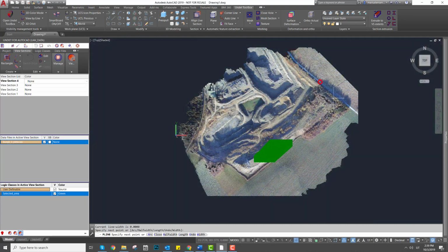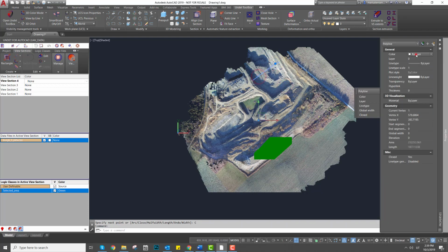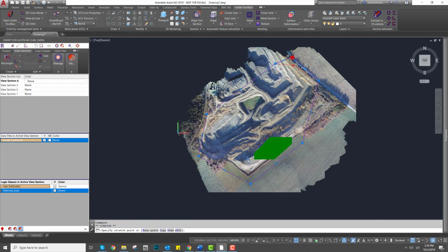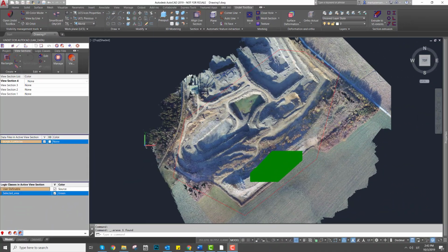Once feature extraction parameters are adjusted, we need to draw boundaries for mesh extraction. To extract the ground surface mesh, choose the Mesh tool from the Undet ribbon menu. Set the grid step to your required detail, select defined area boundaries and set the base point. After Undet finishes calculation, in the command line you will see the created mesh triangle count, which can be reduced before it is loaded to the drawing.